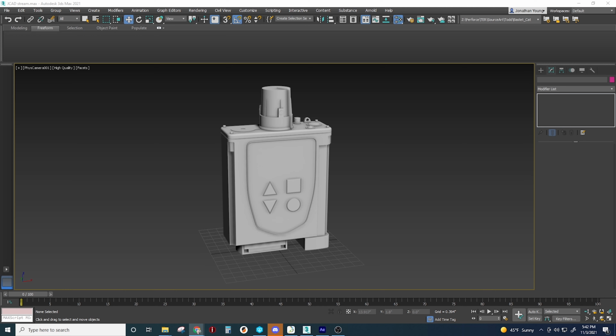Splitting up a model can help with painting parts. Do I need to integrate real hardware into this print? You might have to create something like inner geometry, like a compartment, to house those components. So depending on your answers to these questions will determine how and where to cut up your model. In this case, since we're going to print this object in one plastic, I don't really have to worry about separating any elements because the shape of it is primarily a box, so support material generated is going to be pretty minimal.